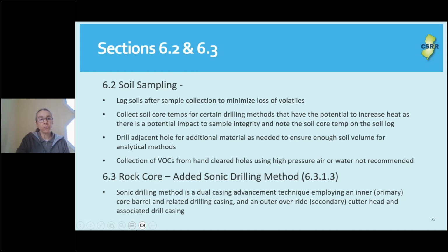Section 6.3 covers rock coring, and in this section, sonic drilling method was added. Section 6.3.1.3, sonic drilling method is a dual casing advancement technique employing an inner primary core barrel and related drilling casing, and an outer override secondary cutter head and associated drill casing. Next slide.